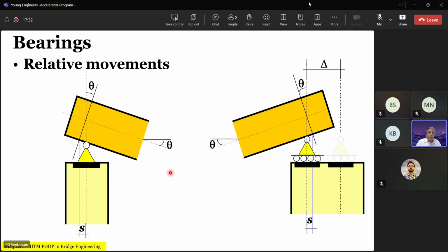But if you notice, you can have this kind of a displacement mechanism at the pinned end, wherein the superstructure undergoes displacement towards the left due to the rotation. And of course, rotation is easily understandable, but understanding the fact that there can be a displacement towards the left depends upon your understanding of the behavior and modeling.